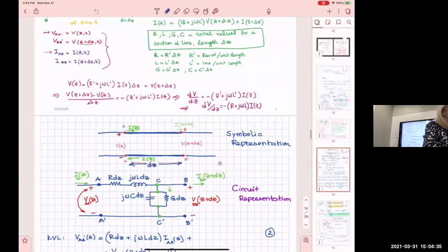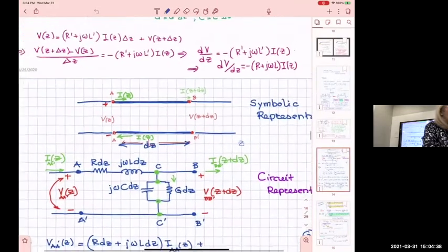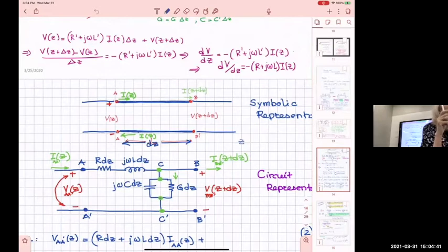What we did is the following. Just to remind you, we started with a real microstrip line. It was ground, and then there are traces on top. A line that is made out of one trace and ground underneath it, separated from the ground by a dielectric, is called a microstrip. This is a fundamental line. You will see it used in most circuits, even the most updated circuits like what you're going to see here, if you were to open one and observe it.